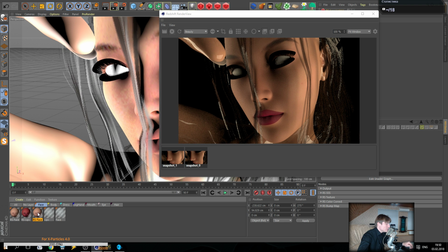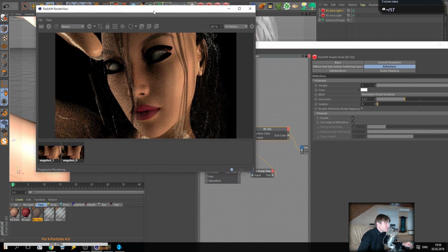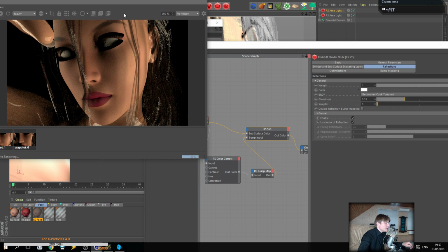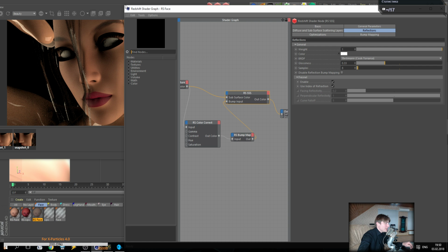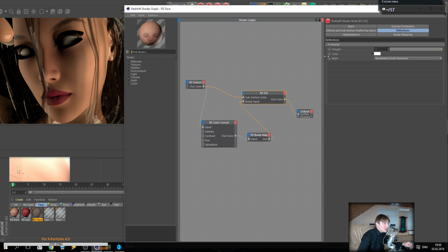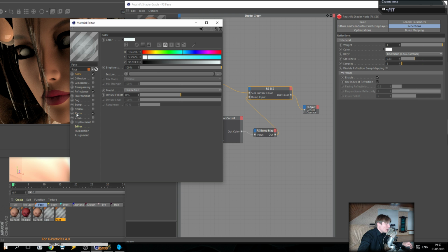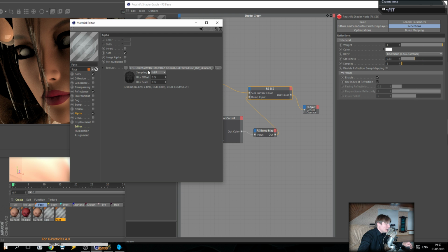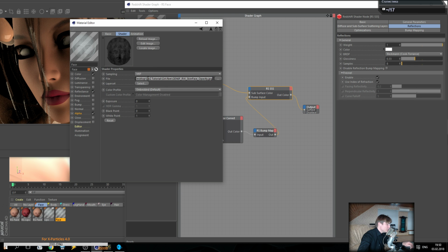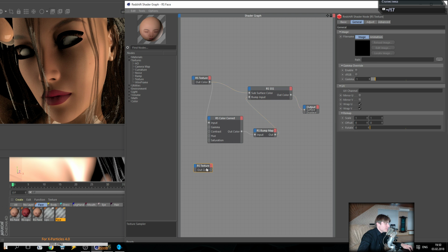We are going to Shader Graph. I have a very small screen. I haven't placed it for all my project, but it doesn't matter. Going here, and what I have, yeah, like this. So take the face, go to alpha, and you can see this alpha texture. Just copy that, create some texture, and put it inside.